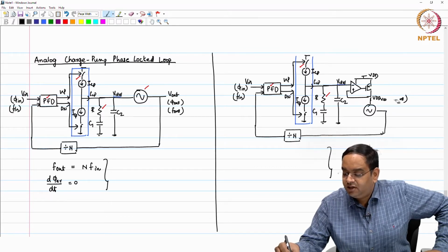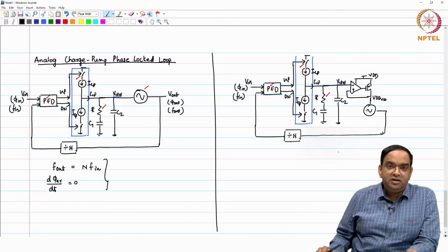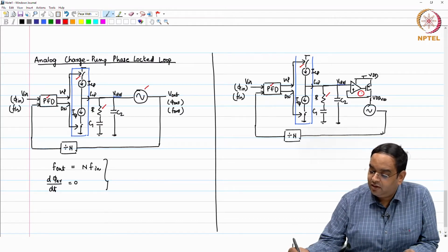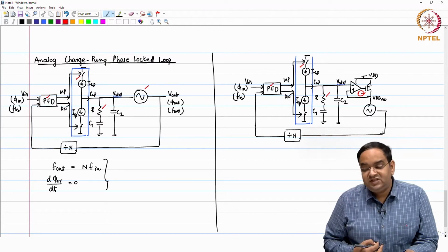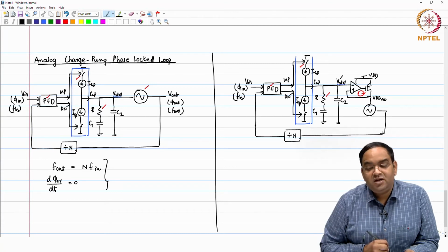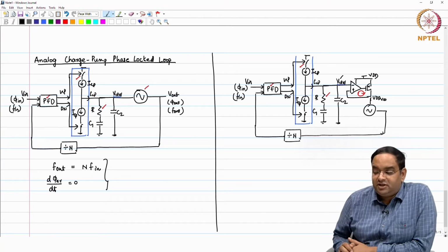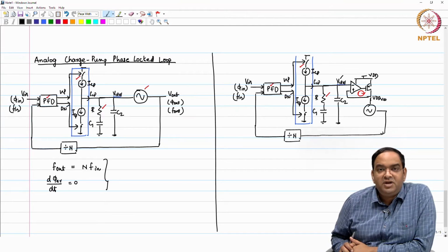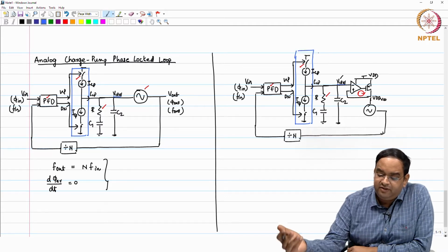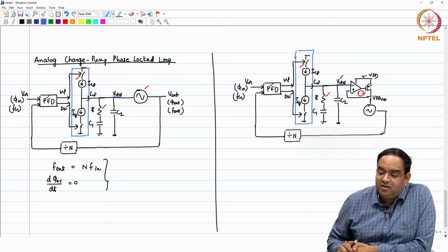So, what happens here then, when you have a supply regulated oscillator, you will have to stabilize this loop also internally, right, and the overall loop should also be stabilized. So, mostly what we do, we design in such a way that from V control to VDD VCO, you have a bandwidth which is much larger than the PLL bandwidth; 4 to 5 times the bandwidth of this regulator loop is quite convenient to design. Okay. So, we talked about different methods in which we can have the supply regulation for the oscillator.